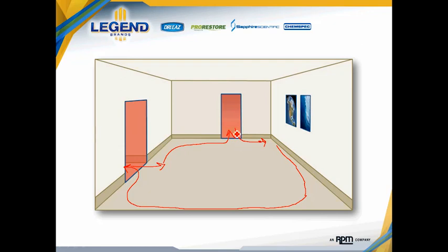And instead of using smaller, multiple, less efficient dehumidifiers, we can centralize and use one larger, more efficient dehumidifier. Not necessarily larger, but just higher capacity, especially with some of the new low humidity dehumidifiers that we have available. A single one of those machines, which draws a third of the power of using smaller, less efficient machines, is very efficiently going to handle the humidity control throughout this entire space, as long as this air movement has been installed appropriately.